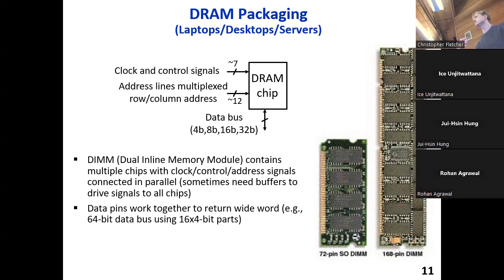It's actually going into the DRAM, going into the different chips, going into the subarrays and the cells, and dragging your bits out. What the DRAM manufacturers invented was this logical collection of subarrays called a bank, which can each be accessed at a single time, but such that different banks can be accessed concurrently. So when you have multiple requests going out to DRAM, it's not that you send a request out and you have to wait until your data comes back to send the next request.